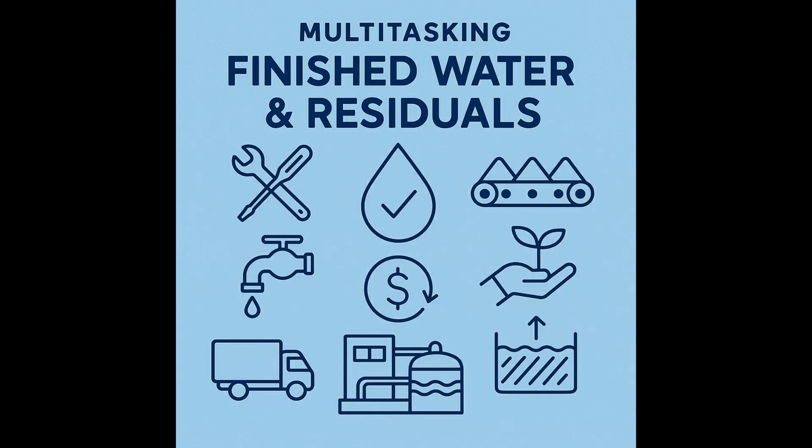This usually involves renting a mobile, trailer-mounted version of the equipment they're considering, like a pilot centrifuge or a pilot screw press. So they bring it right to the plant? Yep. They hook it up to the plant's actual sludge feed for a period, maybe a few weeks or even months. This gives them real-world, site-specific data on how that technology performs with their sludge.